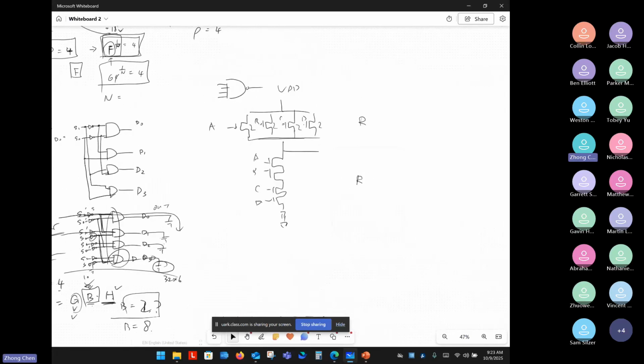For each of the PMOS, you have to assume the worst case scenario: a single PMOS turned on to pull up the output. In this case, the effective resistance has to be equal to R. So the equation is 2R divided by K is equal to R. That is for PMOS, and so K is equal to 2. That's why I have 2, 2, 2, 2 here. So basically the size is equal to the unit-size inverter PMOS.